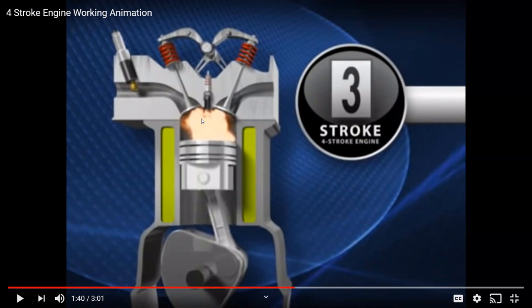In other words, pretend that it happens during an isochoric process, and that's what you saw on the PV diagram. QH got introduced over a constant volume process. So that doesn't really happen here, but it's fairly close, and I have that actual video where you can confirm that. So right now, we've just finished the isochoric introduction of heat, and now we're looking at the adiabatic expansion.